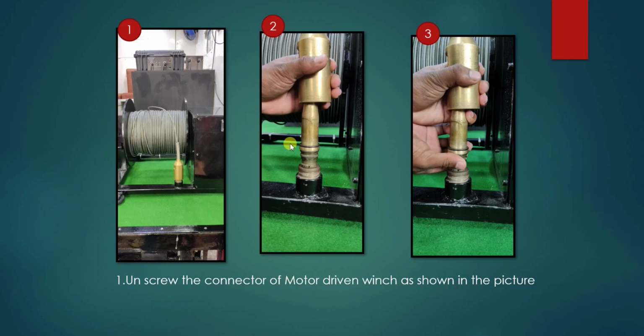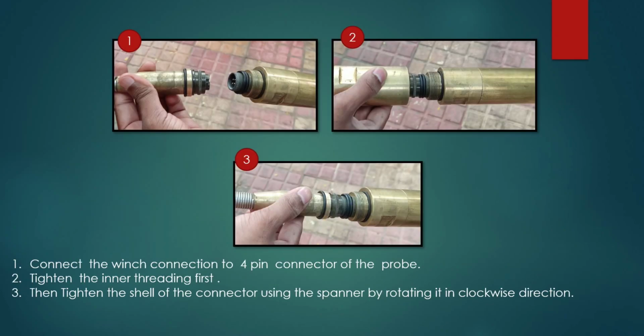And this connector should be carefully removed by rotating the pin and then slowly lifting it up. Care should be taken while joining the connector to the probe, and after that you need to connect the probe exactly. The slit should sit on the 4-hole slit, and then you need to rotate this wheel, and it should make a sound so that the connection is strong. If this is not strong, then automatically there won't be any supply or any communication from the probe.